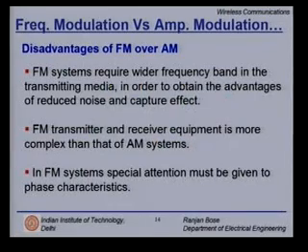We have seen in a previous slide that power amplifier per se is easier and less complex to design in FM transmitters. However, the rest of the modulation circuit for FM is still complex. So, barring the power amplifier part, the FM transmitter is more complex and hence more expensive than the AM transmitter. Similarly, the receiver equipment is also more complex in FM. FM is generally a more complex system.